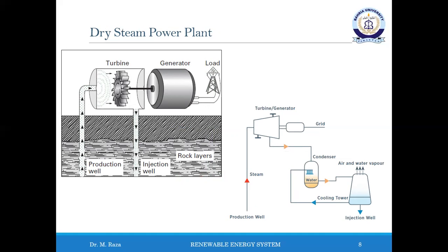At temperatures typical of geothermal fluid, efficiencies are low. High temperatures of 300 to 350 degrees Celsius and higher pressure can produce higher efficiency. But despite use of high temperature, superheated steam rarely exceeds 20% efficiency. In early installations of dry steam power plants, very little spent fluid was re-injected back into the reservoir. This caused the fluid pressure to fall. Later, a re-injection policy was introduced to make the resource more sustainable, and some 70% of the mass of produced steam is now re-injected and field production has been stabilized.